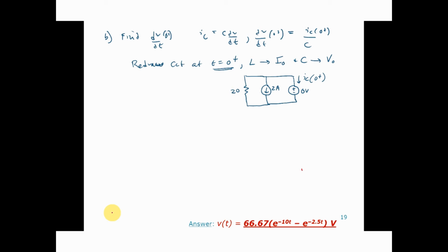Why 2 amps? Because it wants to maintain each of the branches. Do you get what Chris is saying? He's saying that the voltage can't change. In other words, we've got 0 volts imposed across this whole parallel network. That means the voltage drop across the resistor is also 0 volts, right? So how much current is going to flow through the resistor? Nothing, right? So where does all that 2 amps go?